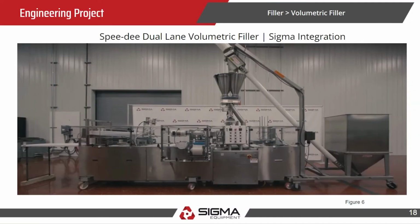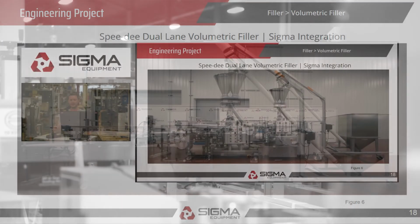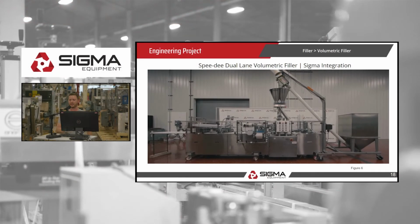So here's an engineering project that we did. We did have video, but it didn't show much of the volumetric filler, so I'm just going to walk you through it. Right there on the right, you'll have your product hopper with an auger conveyor taking your product up. I think this was filling oats into a dual lane cup filler. It's dropping it into your volumetric filler. This is dual lane because it's filling 2 cups at a time. Into the cup filler, going down, getting sealed, and then lidded.